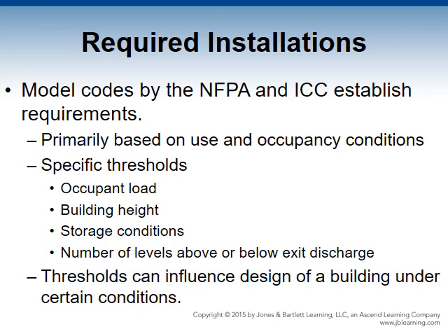Model codes by NFPA and ICC establish requirements for your automatic sprinkler systems. They are primarily based on the use and occupancy conditions. Thresholds specific to use and occupancy conditions actually establish whether the code requires or omits an automatic fire sprinkler system, such as occupant load, building height, storage conditions, and the number of levels above or below exit discharge.